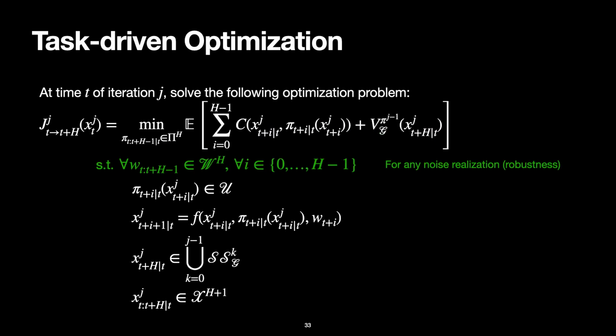We will solve this problem such that constraints are satisfied for all noise realizations. Note that while we desire robust constraint satisfaction, we are optimizing the expected sum of costs and not the minimum sum of costs. The same results can be proved with a little less machinery for the minimum sum of costs, and this does not require knowing the distribution of noise disturbances. In practice, however, this may be a pessimistic strategy, so we focus on the expected sum of costs here.